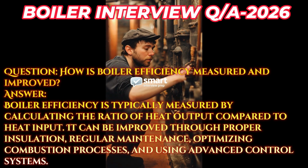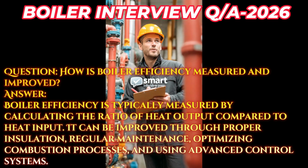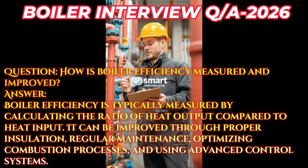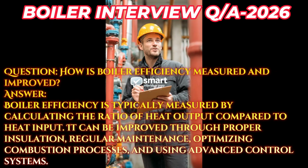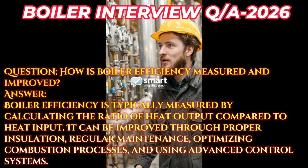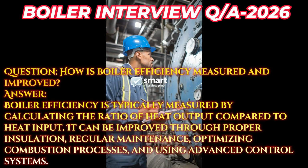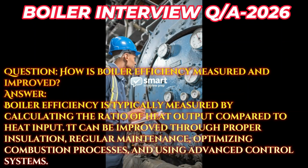Question: how is boiler efficiency measured and improved? Answer: boiler efficiency is typically measured by calculating the ratio of heat output compared to heat input. It can be improved through proper insulation, regular maintenance, optimizing combustion processes, and using advanced control systems.